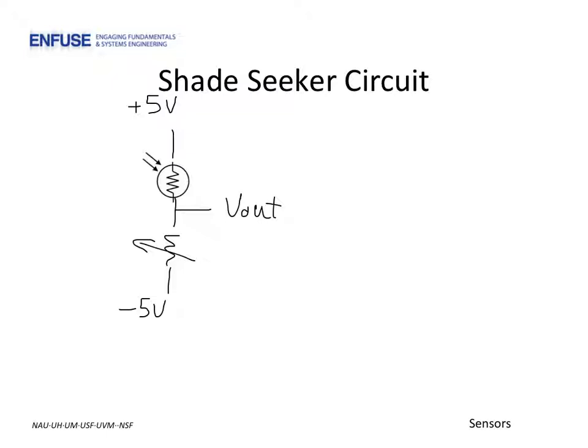Now, when the light intensity increases, this causes the photoresistor to become more conductive, thereby reducing the resistance. Therefore, more voltage is dropped across the potentiometer, and that causes Vout to become more positive. And again, as with the thermistor, you could take this voltage output and create an analog system with the comparator, or again, just take this output and bring it into a microcontroller.